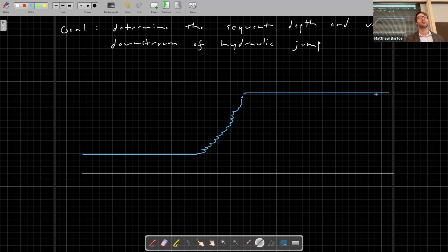It's going to decrease, right? So typically, if we're installing a culvert that is going to carry water into some natural stream bed, we want to reduce erosion as much as possible. Erosion is caused by very rapid flows typically. So typically the larger the velocity, the more erosion you'll get. So we often want to induce a hydraulic jump to limit erosion or limit other damage to the channel downstream.